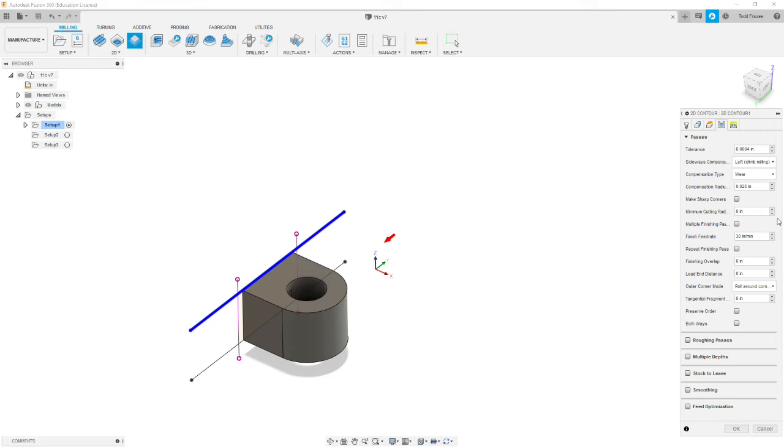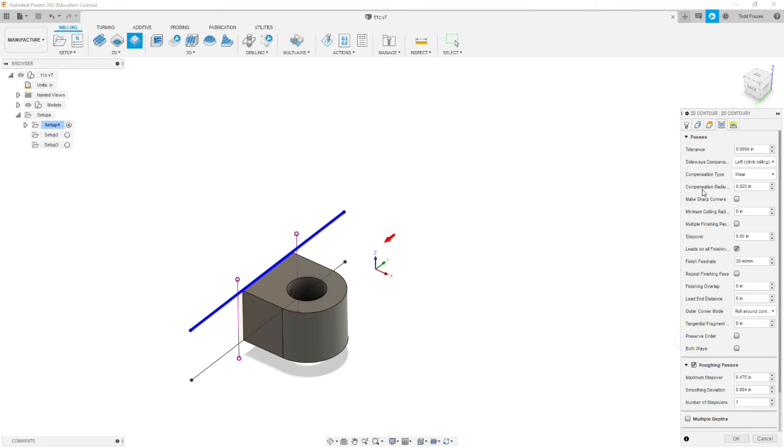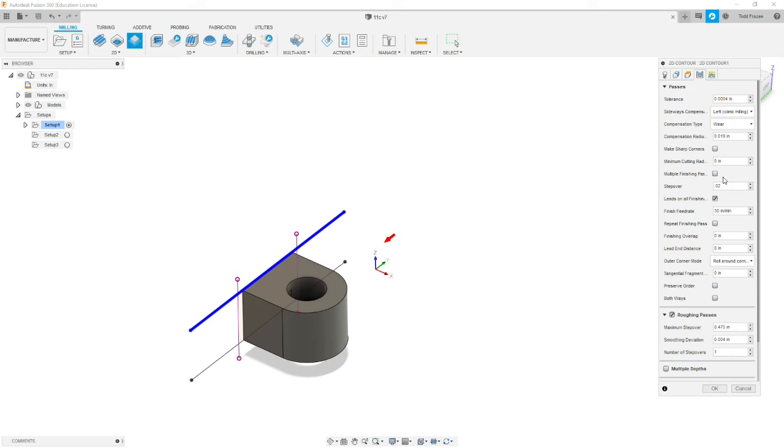and we're going to scroll down until we get to roughing passes. Once we select roughing passes, it gives us the ability to put in a finishing step over. And 50 thousandths is a little much, so let's change that to 20 thousandths. Most of these other boxes should be all at default. And we're going to do a maximum step over of 80% of the diameter of the cutter. That assures you full cleanup.